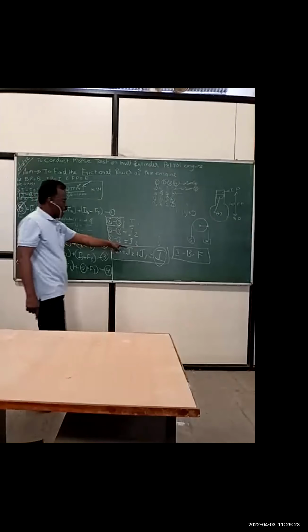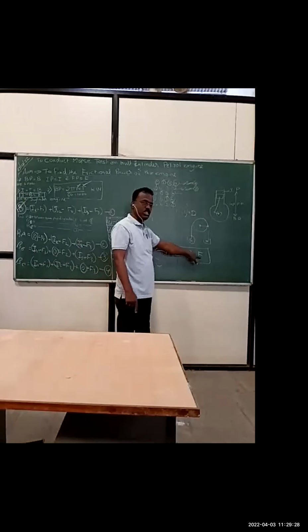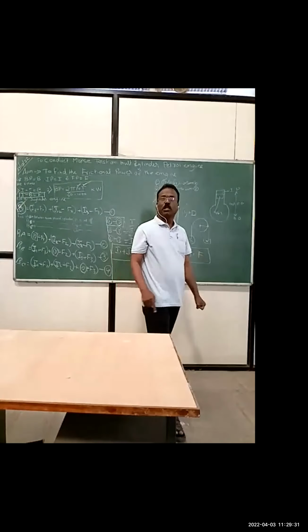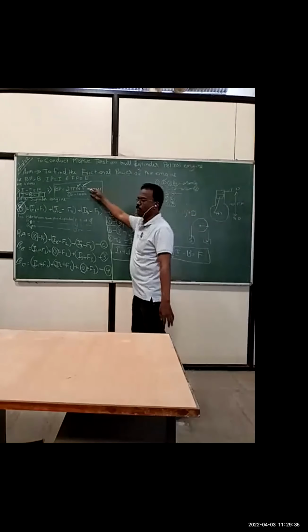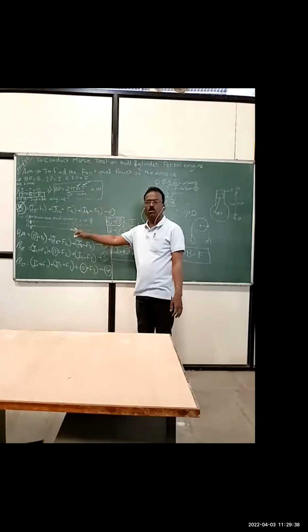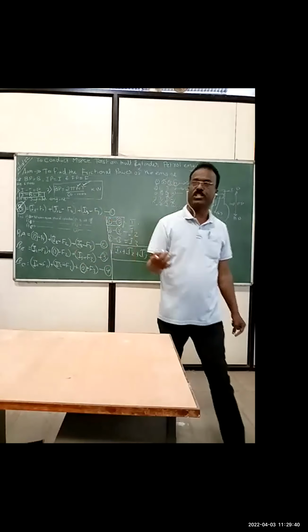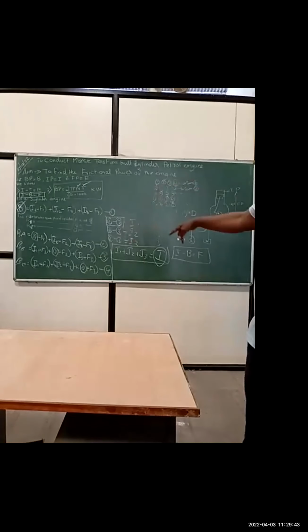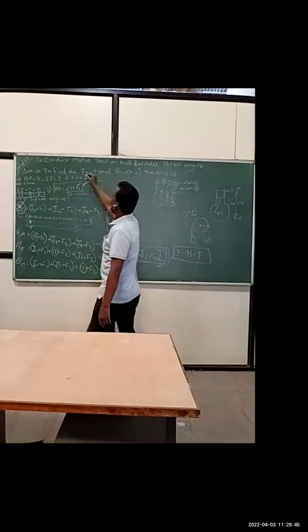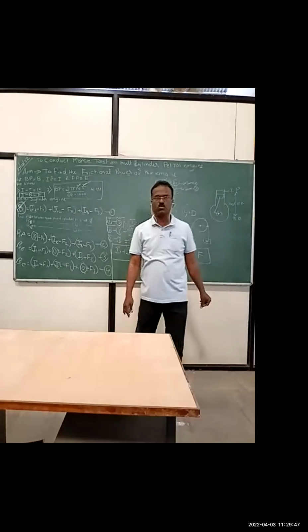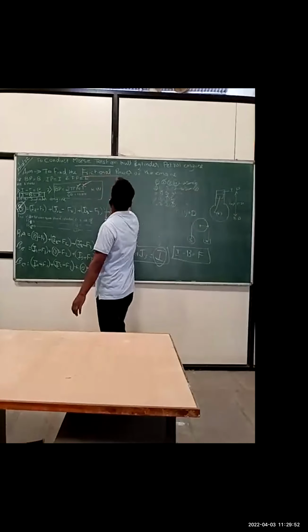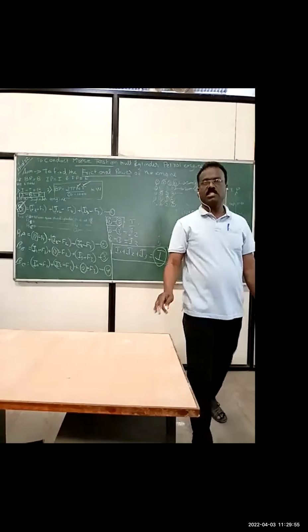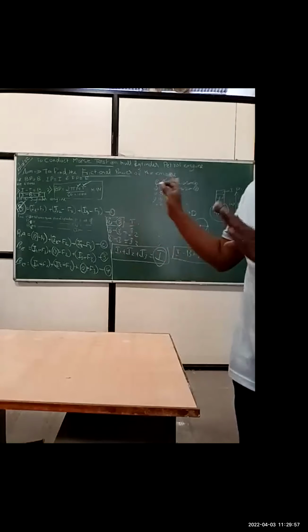So now, I minus this B, I minus B is equal to F. So without going for anything else, just finding out the brake power of the engine, we are able to find out the frictional power of the engine by this particular arrangement. And this is what you call a Morse test. And what is the Morse test done for? To find the frictional power of the engine. So if we want to find out the frictional power of the engine, we use this test.